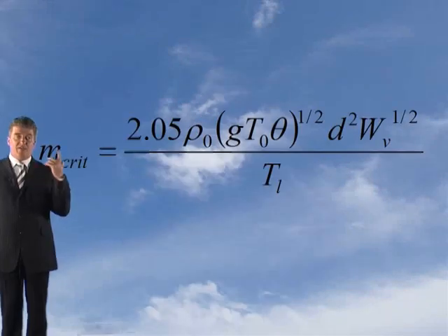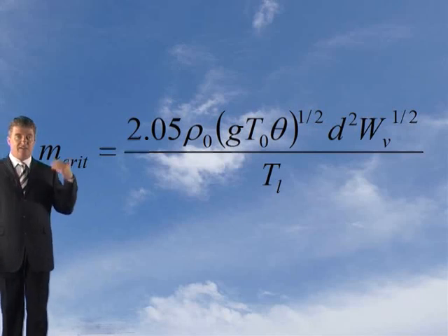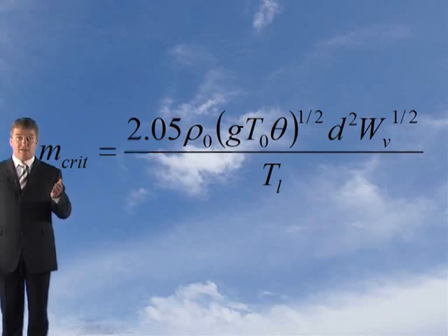Now don't forget again, there are 2 models to determine if plug holing will occur, and this depends on where the ventilators are located. There's one where the ventilators are located within 2 metres and there's one when it's more than 2 metres. In this case, the ventilators are more than 2 metres away from the edge, and this is the formula we apply. This is the MCRIT formula to work out the plug holing check. MCRIT is the maximum rate that it can be extracted without plug holing.